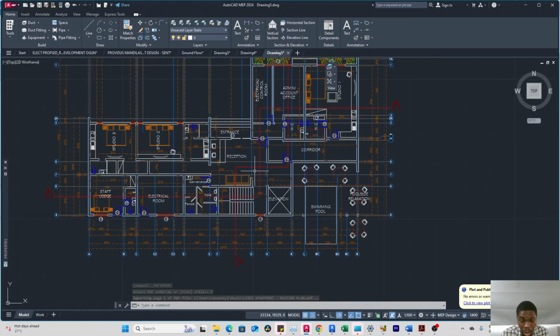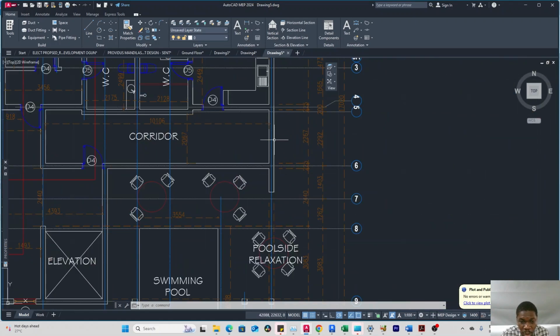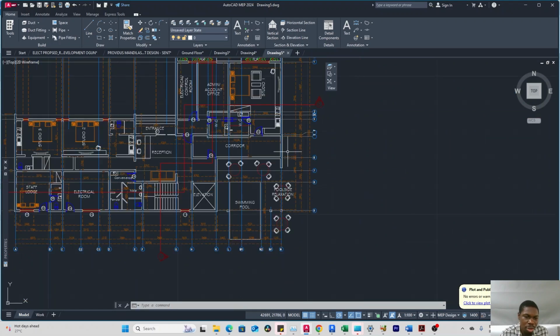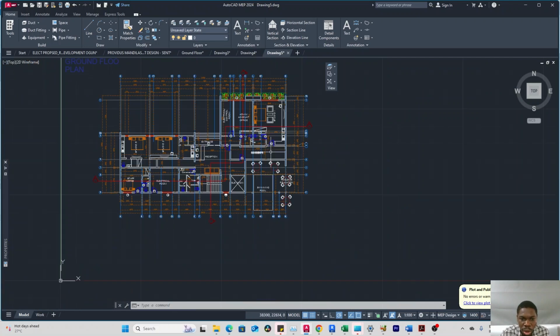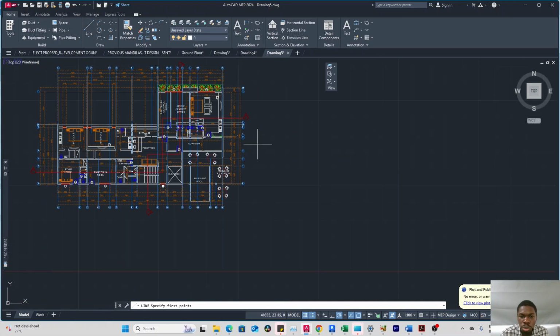So, going with the approximate rule of thumb that this block wall is around 225 to 230 for just a normal building. However, note, if the building is high rise, maybe 8, 10, 12, 13 floors, there is a probability that this external wall might be a little bit bigger, maybe 260. With what I've seen so far, 260. So let's use that reference to go about scaling our drawing. With that in mind, I would like to use 225 in this case.